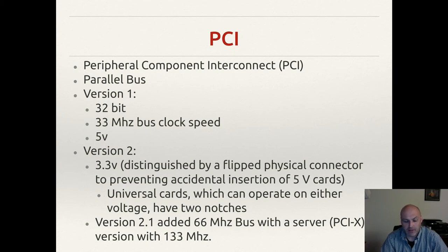realize that that means you would need completely different peripheral cards probably if they didn't have proper regulation, and that's true. So what they did with the socket is they flipped the way the physical connector was so that there was a divot and you couldn't plug a 5-volt card into a 3.3 and vice versa. So you couldn't fry your cards, but there was a shift there where it kind of made old cards defunct and you had to move to a newer one.